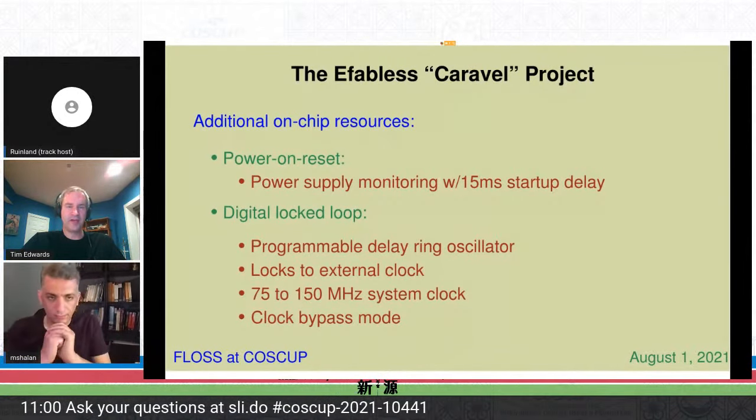For the power supply connections, we do make one concession to the operation of the place and route tools by having a set of pre-placed power and ground rings at the perimeter of the user project area. The place and route tools are expected to see this power ring and connect to it as needed. The user area is considered to be inside the area of those power rings, although the place and route tools can connect to the power rings outside of the user area boundary. Everything else outside of the user area boundaries is off limits to the designer.